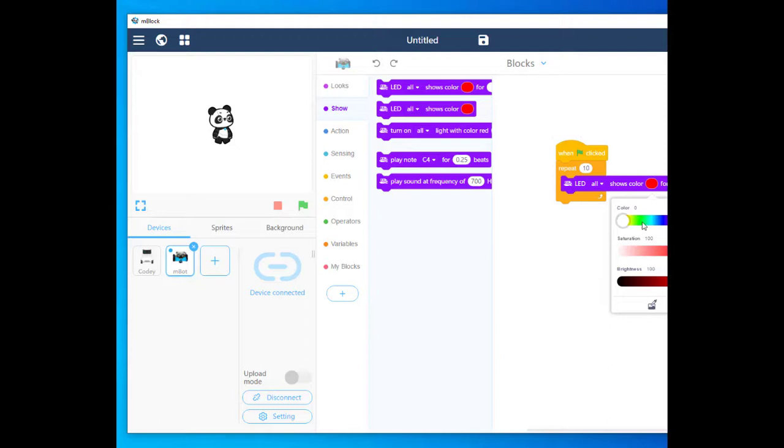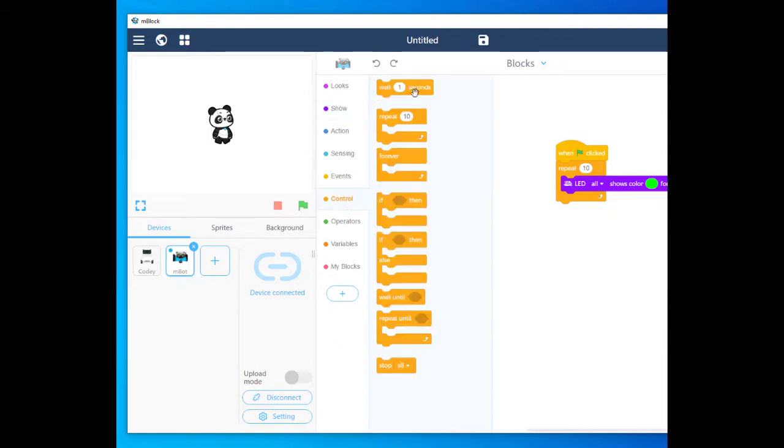And then I would like to have a different color than red. I will say green. And then I'll also put a delay saying blink. And then wait for 1 second and blink again. Wait for 1 second. Actually, it already has a second, I'll leave that anyway. That means there'll be a 2-second delay between these. And then once this is connected, I can just click on this, and the robot should blink the green light 10 times with a 2-second delay between them.